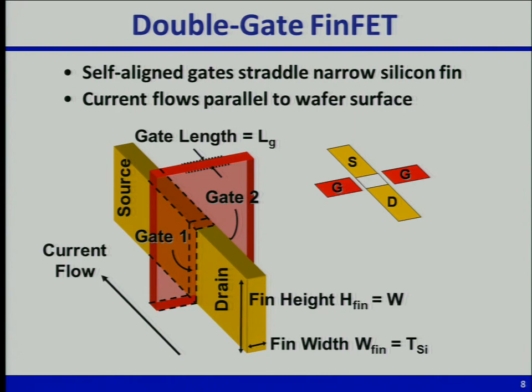So he came to Berkeley, and he was the very first person to make a nanometer scale vertical transistor. So what we did at Berkeley, just to summarize, was decide that the best way to make a double gate MOSFET is to rotate the silicon on its edge. So this width here now is that body thickness, right? That body thickness has to be no more than 2/3 or 1/2 the gate length. So the width of the fin has to be narrower than the gate length, which is the separation between the source and drain. And then you have the gate electrodes straddling the silicon fin to control current flowing along the side walls of that fin between the source and drain regions.